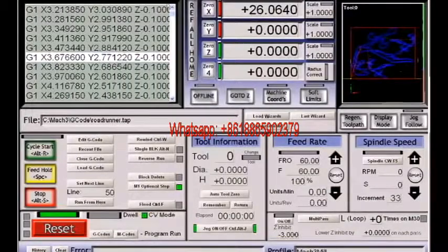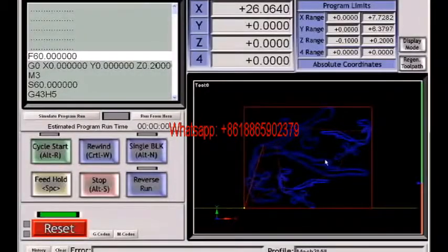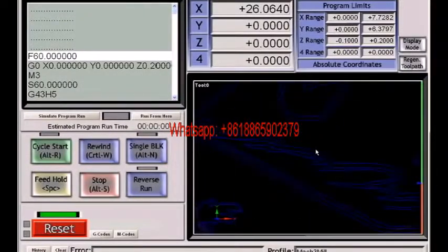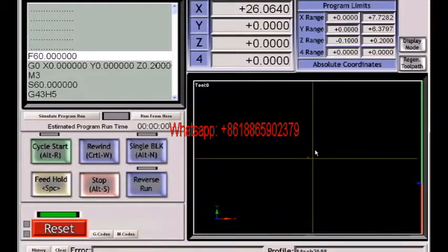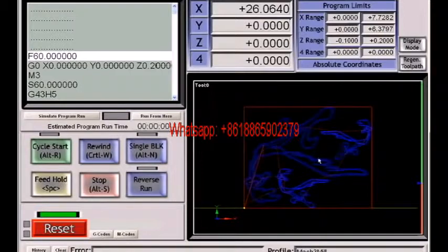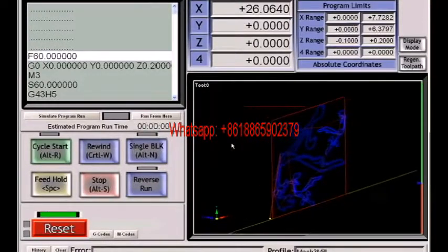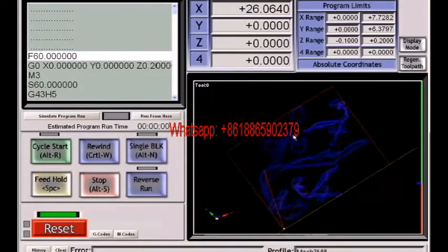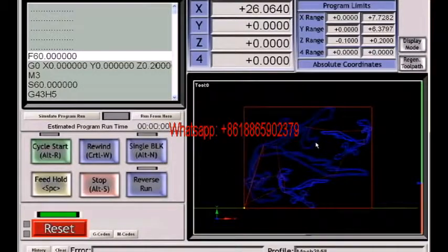We can take a closer look at that toolpath by going to the toolpath window. Now you can see once I've clicked in the window, if I rotate my mouse wheel, I'm zooming in and zooming out. Double-clicking resets us. You can see the dashed lines are rapid moves between cutting segments. The dark blue lines are actual G1 feed lines, and if there were light blue lines here, those would be G2 or G3 arcs. You can rotate it by clicking in it and rotating around. Again, if you get lost, double-click and you're back to normal.